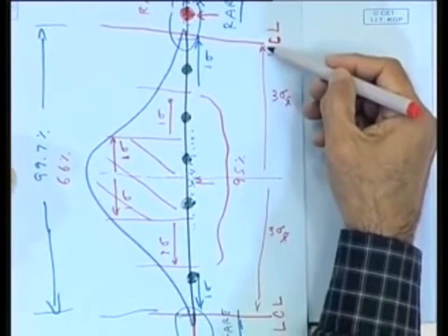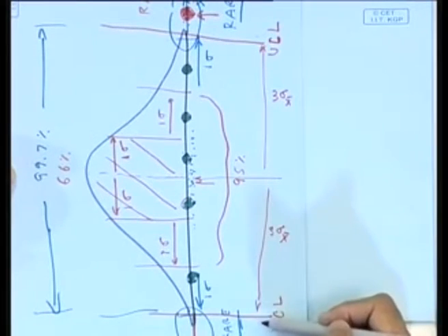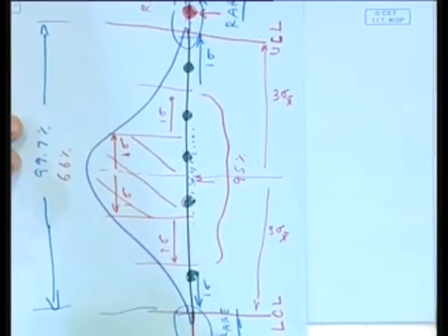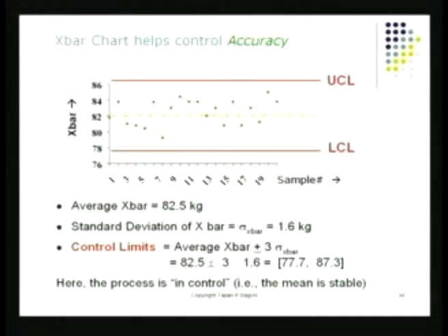So my control limits are located just to indicate the beginning of those rare events. And this is exactly what I've got on my screen here. Notice my screen here, I've got the red line going as upper control limit, I've got the lower line going as lower control limit. These turn out to be the limits. Within that, I've got my natural variation. Anything beyond that is a region where, if a point falls there, I need to investigate the process.